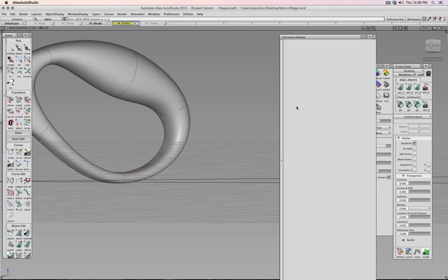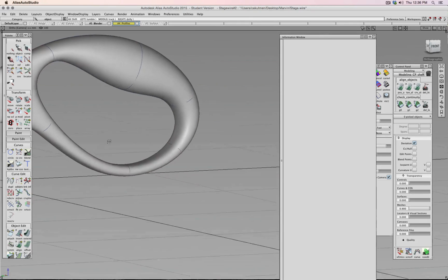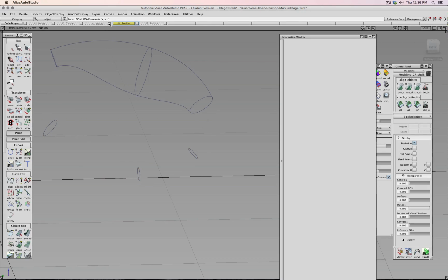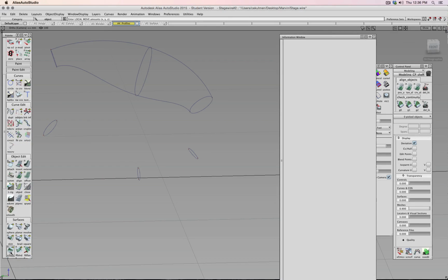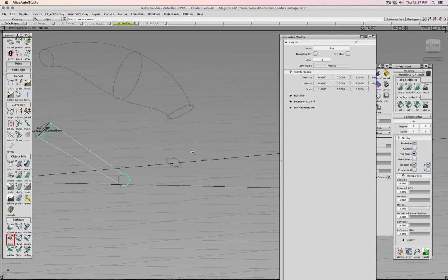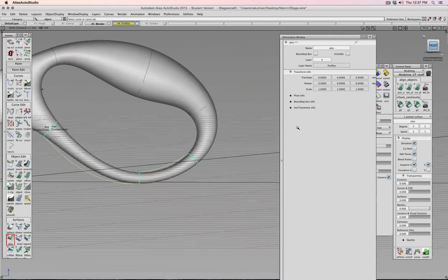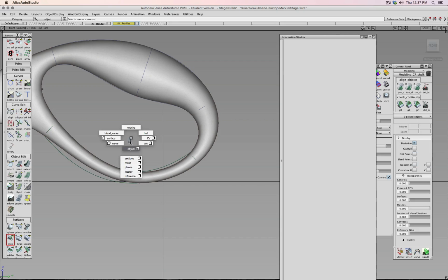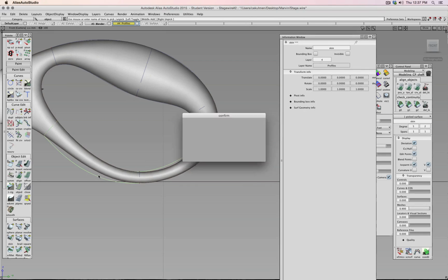And now let's see, for example, what happens if we just skin those. So I'm not going to use a rail. Skin you, oops, skin you, you, and you. Let's take a look if, for example, this hits it, and it hardly really can. So, nice try, doesn't work. We need rails.